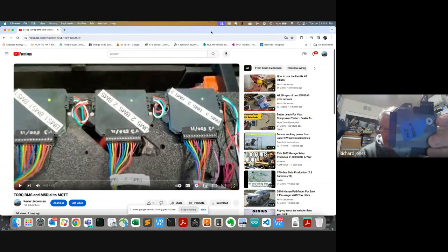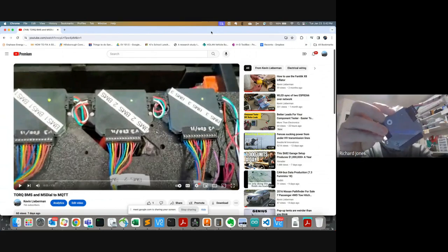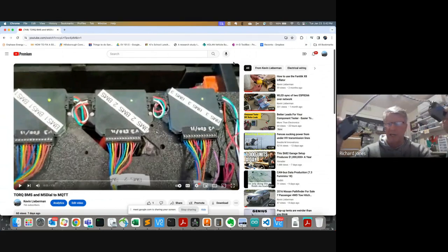And each one has a little selector on here, an ID, which basically changes that address we were talking about on CAN bus. So you've got to have them all on different addresses. Otherwise, if they're on the same, they'll be overriding each other with different data. And that can happen as well. So you need to make sure everybody has their own address. And conveniently, these guys have this little rotary switch to very easily change that when you set up your vehicle or if you're doing experiments.